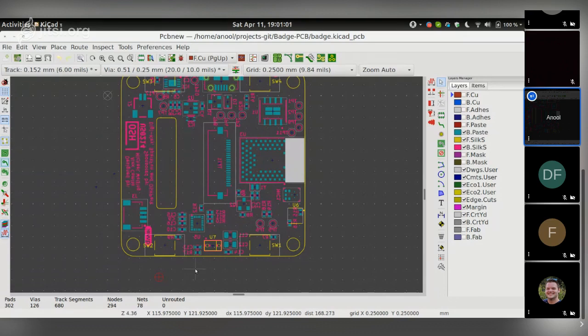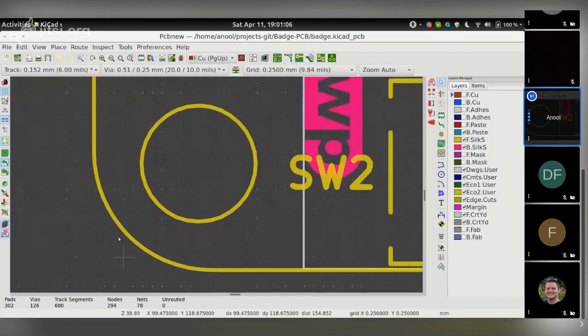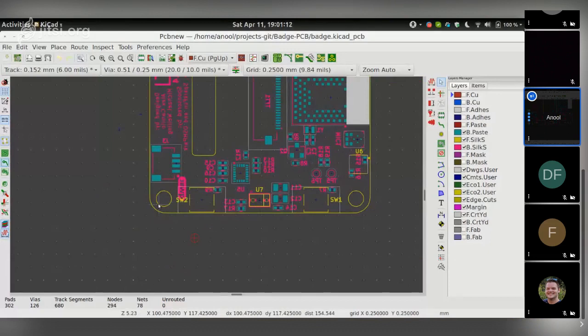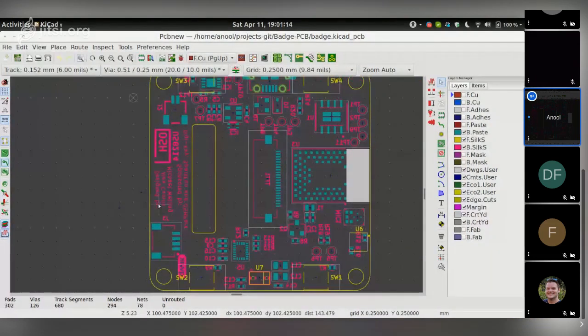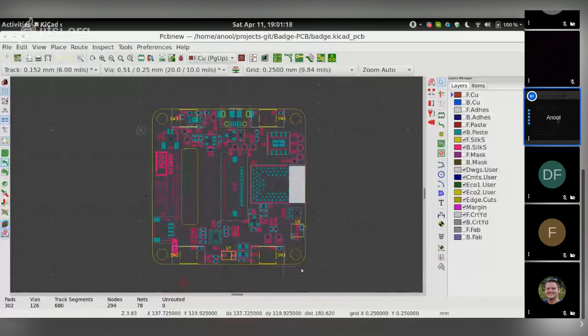So the other thing is, because the arcs and circles get broken up into line segments, once you bring it into KiCad, it might become difficult to move the whole edge cut outline layer as one unit without first having to actually hide all of your layers and turning off the layers that you don't see, then grabbing all the elements on edge cuts and moving them.